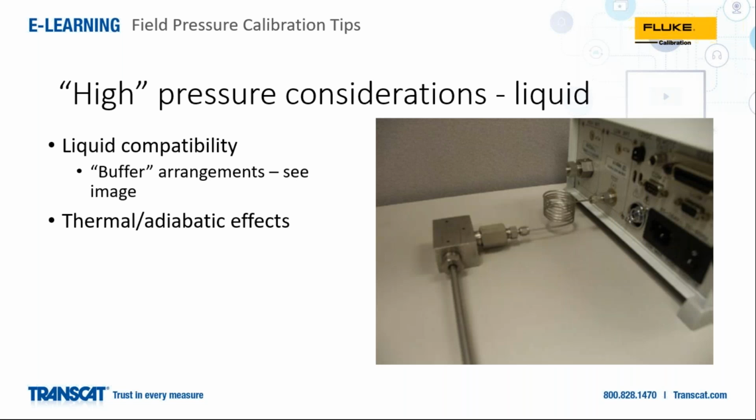Considerations with liquid is primarily liquid compatibility. So the devices that you're testing, are they compatible with any sort of a liquid? Which liquids are they compatible with? If you're doing pressure calibrations of a drinking water system, let's say, you probably don't want to use a fluid that is, say, petroleum based.